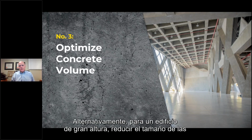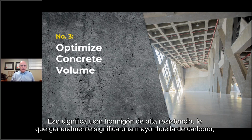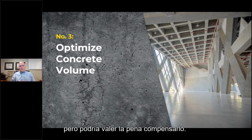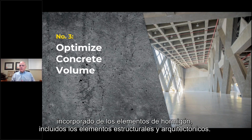Alternatively, for a high-rise building, reducing the size of the columns might be critical to keeping the rentable space to a maximum. That means using high-strength concrete, which generally means a higher carbon footprint, but it might be a well worthwhile trade-off. We suggest using life cycle analysis software to quickly calculate the embodied carbon of concrete elements, including structural and architectural elements.